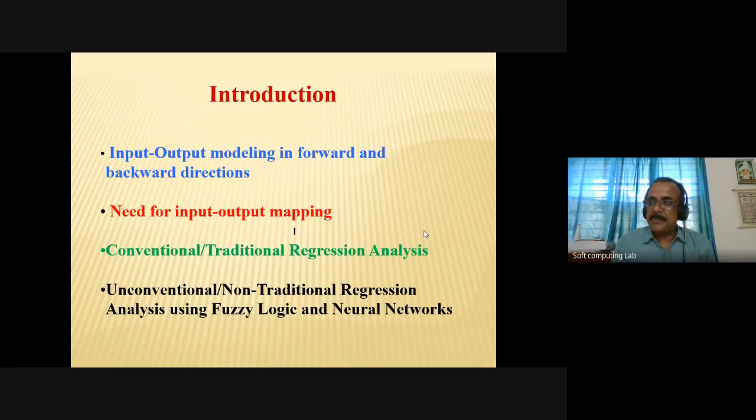And what is the purpose of straight turning? The purpose of straight turning is to reduce the diameter of that particular shaft, and at the same time, the surface finish should be very good. That means the surface roughness should be as minimum as possible. Now, how to do that? If you just rely on one experienced operator, how does he do it? On the lathe, he will be selecting a few parameters. The parameters are nothing but the cutting speed, feed, and depth of cut. So depending on the requirement, the operator is going to select cutting speed, feed, and depth of cut, and he will be doing the turning on the lathe, and he will be getting a very good turned surface, with very good finish or the minimum surface roughness.